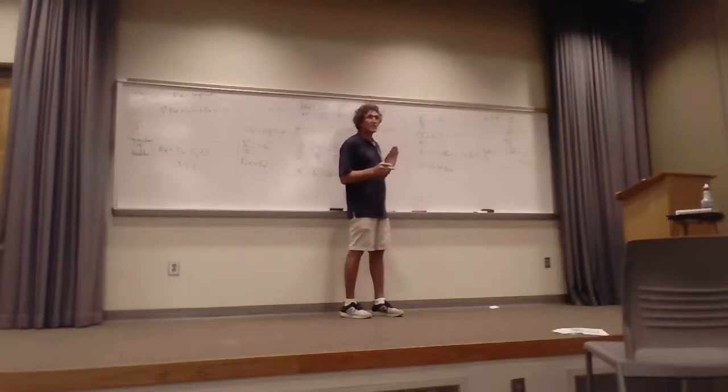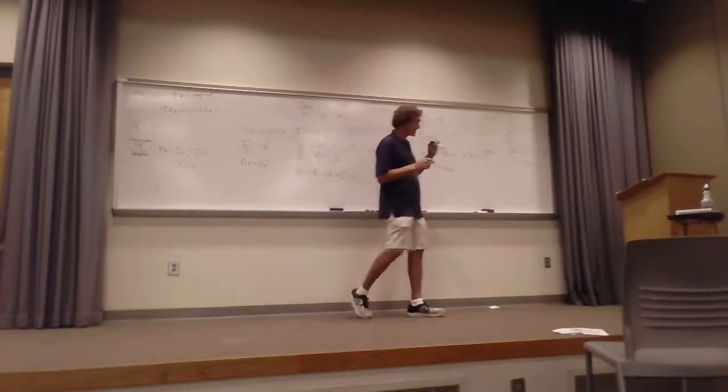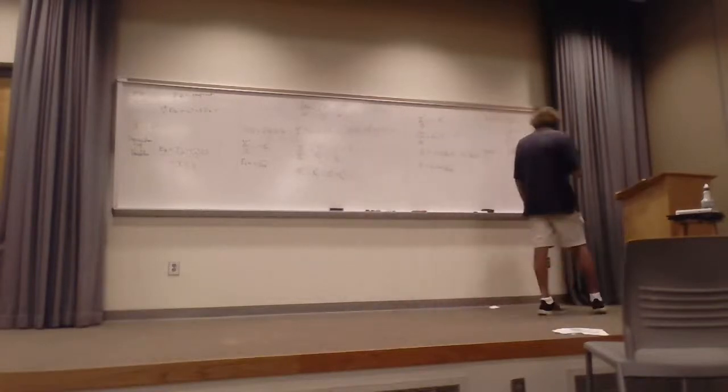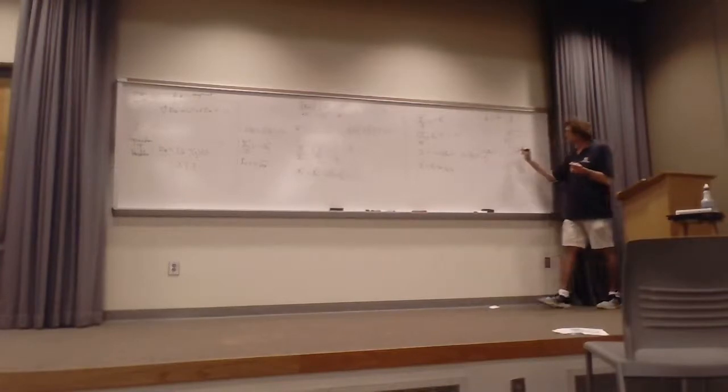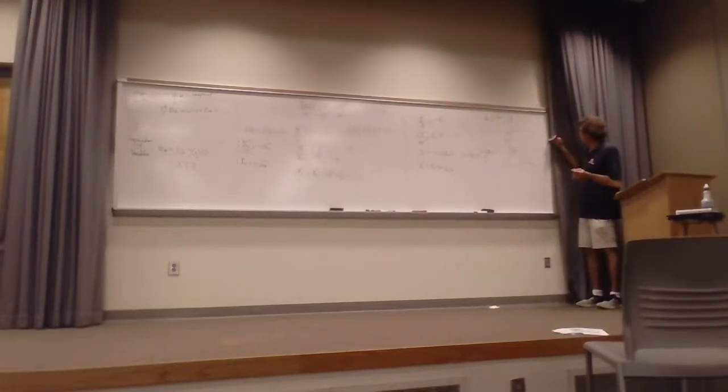Now, how do we get the value of beta x? Remember, this is how it varies with x. This is the z component. Well, I know here, when x is right here, it's 0. The sine is 0, checks that box. Where else has this got to be 0? Right here, right? Because E_z is going in that direction. It has to be 0 at this edge when x is equal to a. You all see that?